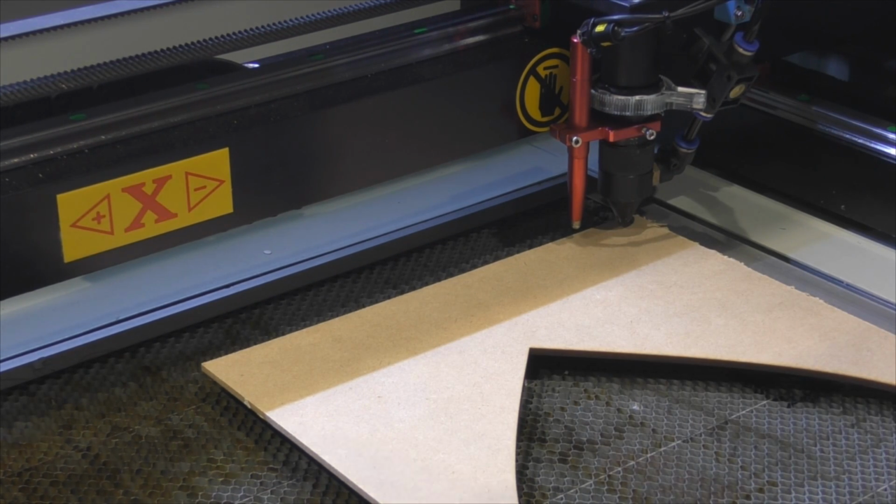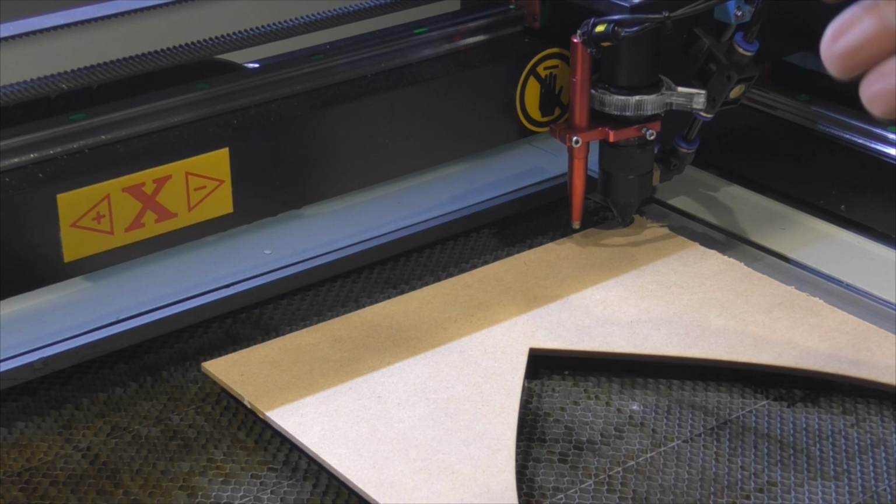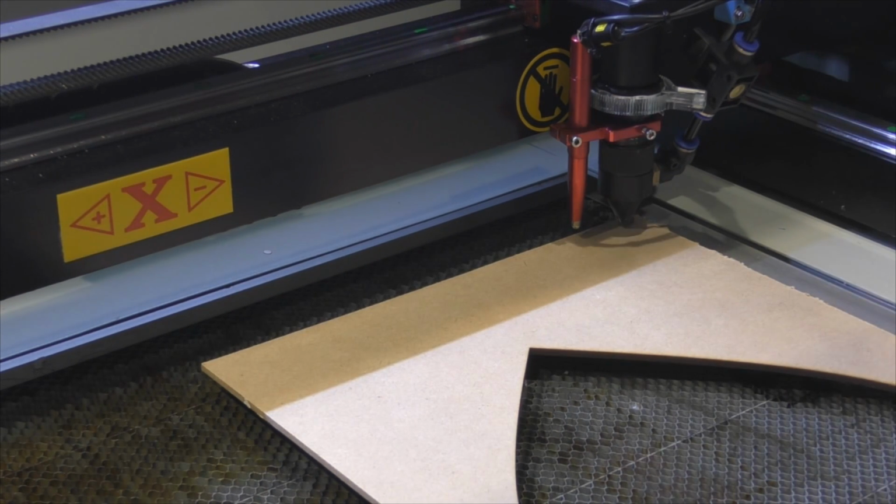My suggestion is always use the maximum power that you can. I'm going to set the parameters to 67%, which is the maximum I can run on this machine. And then I'm going to set a fairly slow speed. This is a guess. This is experience. This is a finger in the air, but at least we shall find out, because if the square does not drop out, we're going too fast. And if the square does drop out, we're not going fast enough. So we can't lose whichever way we go. We've eventually got to get to the point where the square doesn't drop out. So we'll start off at something like maybe 4mm a second, very slow.